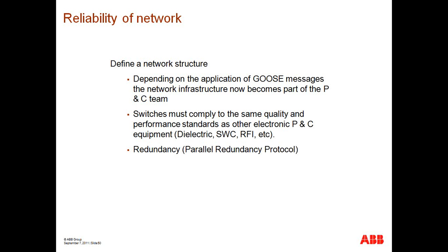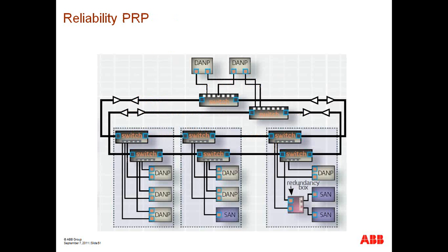there are standards for dielectric surge withstand capability and RFI with which equipment needs to comply. So you'll start seeing RuggedCom, GarrettCom, and other switch manufacturers stating that they're 61850-3 compliant. And actually, what that means is that they comply with all the type test information that's defined in IEC 61850-3 in regards to dielectric surge withstand capability, radio frequency interference, and so on.